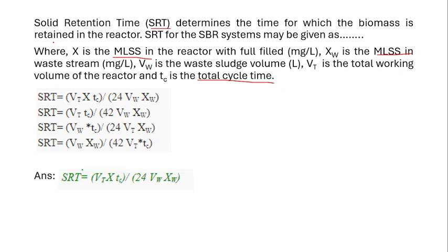So the correct answer is: solid retention time SRT is equal to, first we have to write VT, which is the total working volume of the reactor, into X. X is the MLSS in the reactor at fill. This MLSS is the X here.